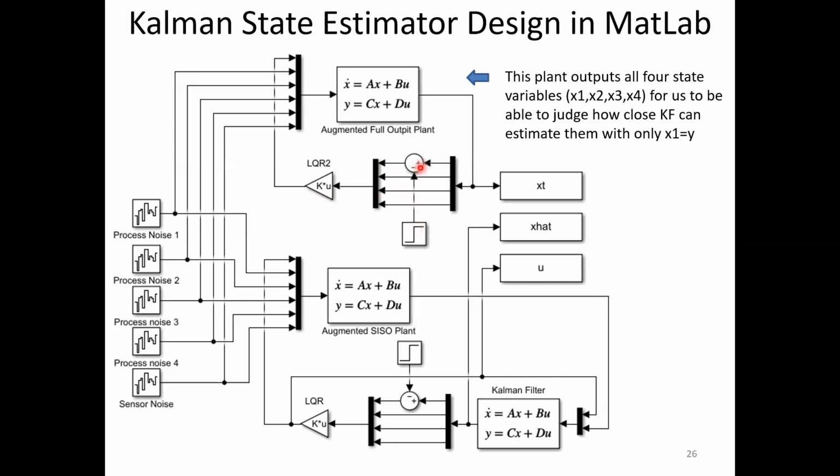So therefore, what we do is we deduct the actual reference. Let's say we want reference 1, we put it like negative here. So it will be -1, right? If you get it over here 0, actual 0, it comes as -1 over here, and the LQR will try to bring it up to 1, right? So then the first state variable moves up to 1. So when it is 1, this is 1 minus 1 is 0, then LQR is happy. It thinks state variable 1 is at 0, but actually it is at 1, at the reference value, right?